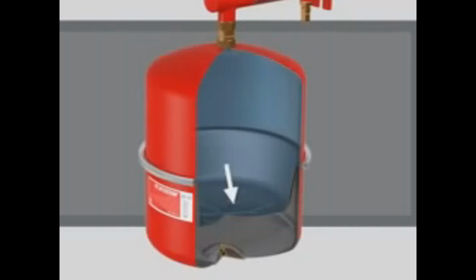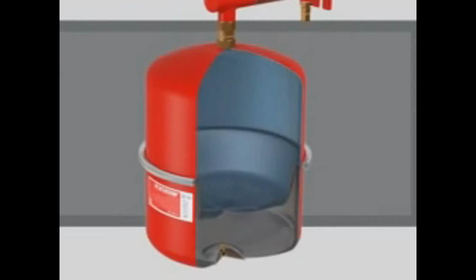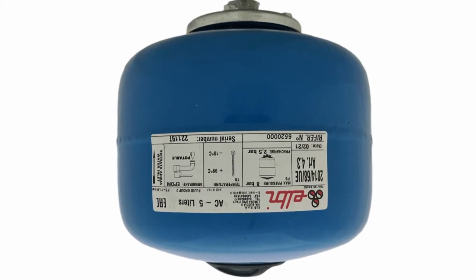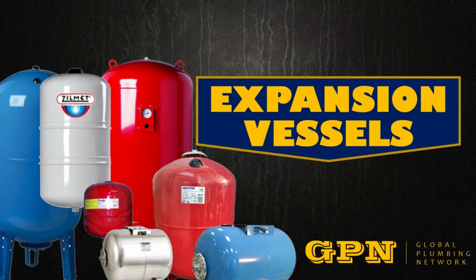The flange of the vessel should be at the bottom, so the dirt that comes with the coolant comes out. Vessels are recommended to be installed with the nipple down, so that the air that gets inside the tank has a chance to leave it and does not accumulate. That way it does not contribute to the corrosion process. This is especially true for diaphragm vessels. Some tanks even indicate the direction of placement of the entrance to the vessel.